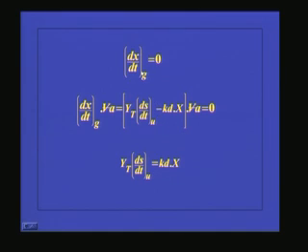Or we can write it like this: dX/dt growth, the biomass growth, is equal to 0. If you write the mass balance equation, dX/dt growth times Va, the total change in microbial concentration in the aeration tank, is equal to YtQ minus Kd times X times the total volume.